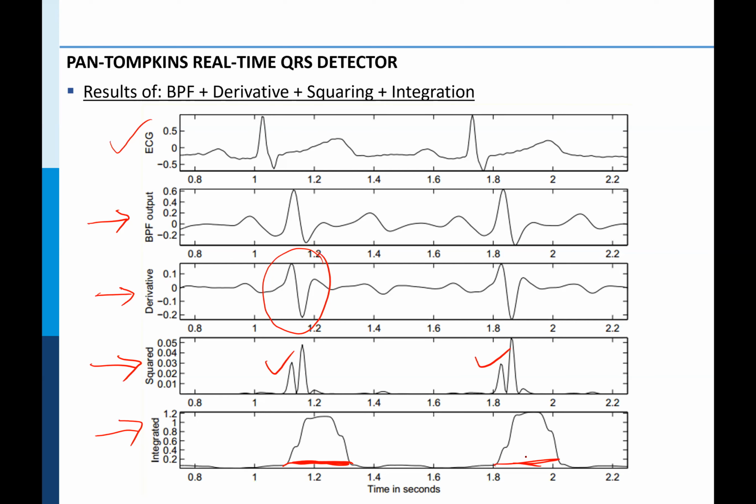Now the question is, how would my algorithm, following the moving average, detect two peaks? You could apply a simple threshold like this, count whether your signal has crossed this threshold, and use some kind of logic to say there are only two peaks.